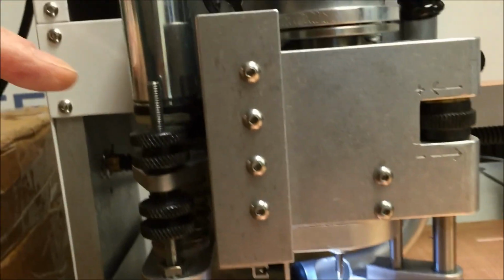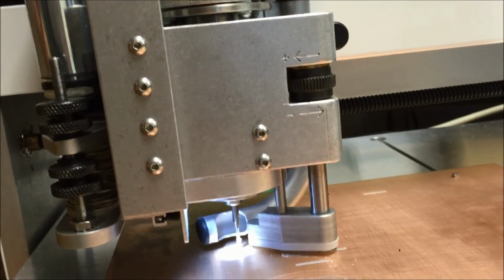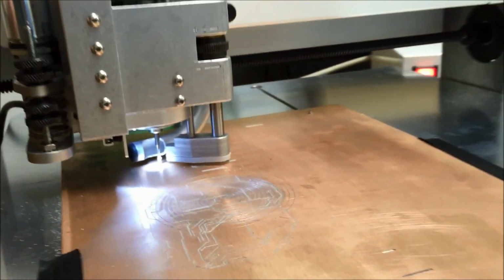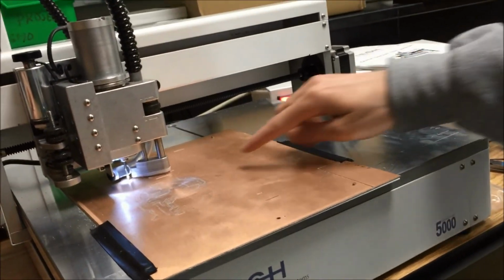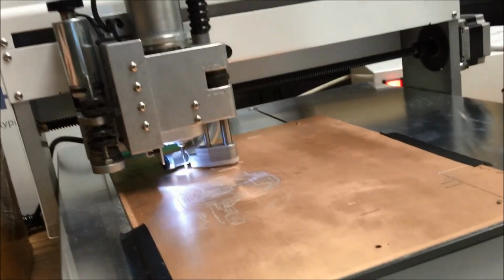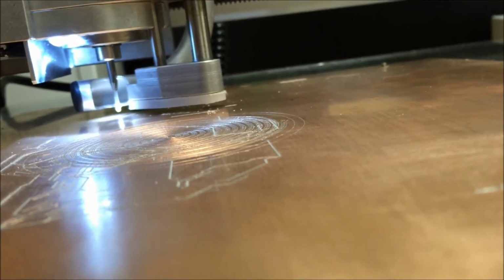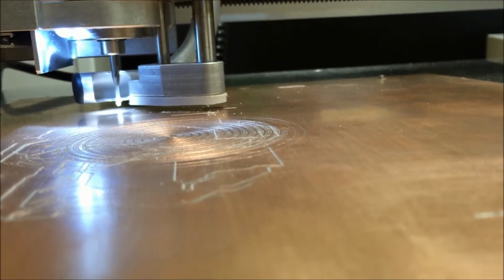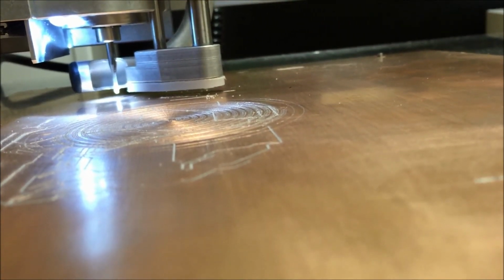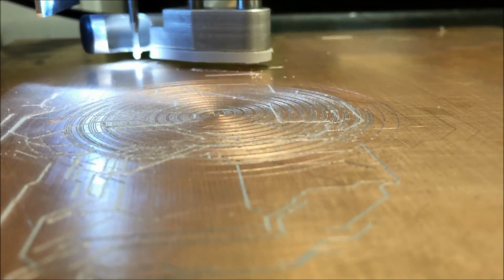So you would set that for your optimal depth, I suppose. You can see there's a lot that can go into this thing. Two screws, okay. And why do you care about the upper limit? Why do you care how high? Because the way the machine works is it uses this stopper foot to tell when it's actually contacting the board material. So if it's set too high, I guess there will be too much Z-axis force once it hits the board, which could damage the tool and decrease its life. And that's just something to be avoided in general.